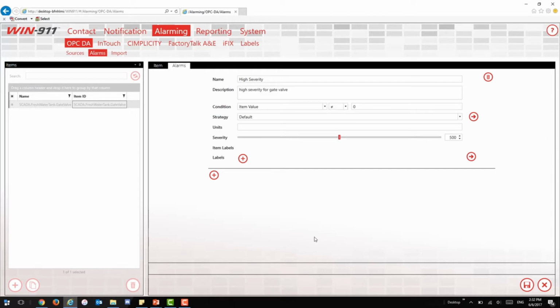That is returned back to us. And then we've defined the alarm condition as far as when the alarm should happen. Now, when it does happen, what do we do? So we're going to associate the default strategy, which is to notify everybody. If you've created new strategies, they'll appear here. You could do default or do not notify, which is don't tell anybody. We're going to leave it as notify everybody. And then again, any units of measurement that are applicable.